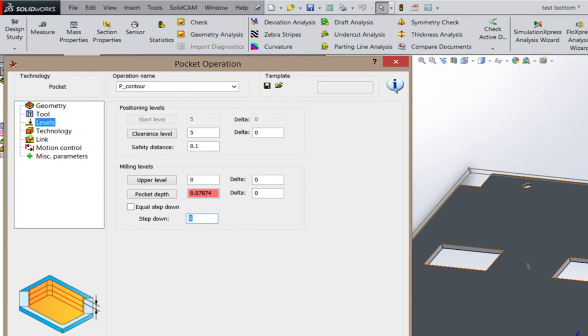So half of an 1/8 is a 1/16, which is about 62. So this would be well over that. But as you get smaller in diameter, that less than half gets even less. You want to take it easy on that end mill because it's kind of wimpy. If you look at an 1/8 inch diameter end mill and you kind of flick it with your finger, you could probably break it with your fingernail if you tried hard enough. So we want to be not so aggressive here.